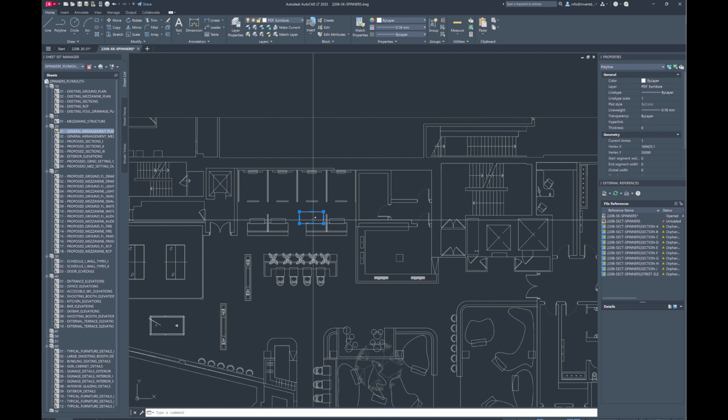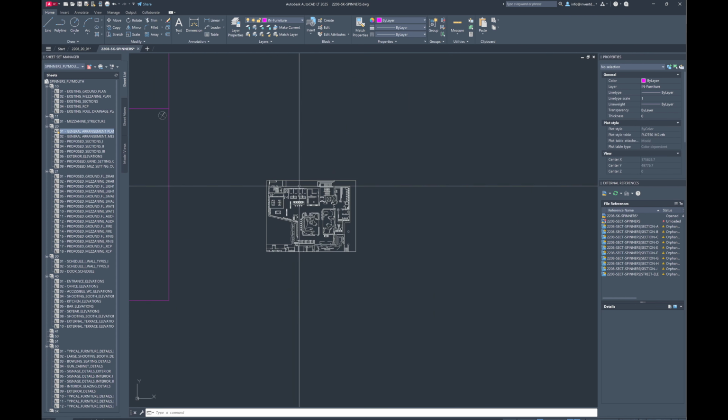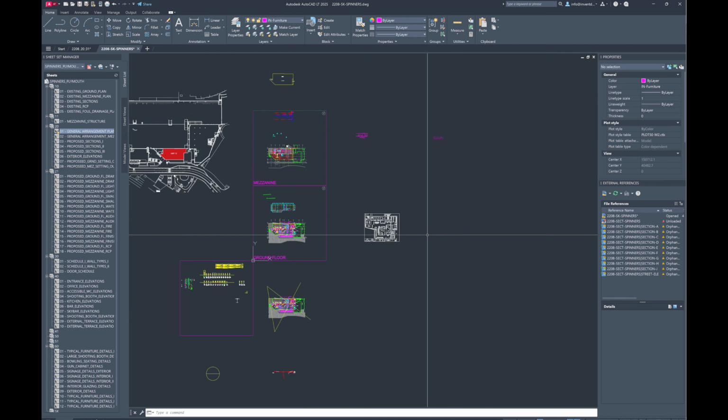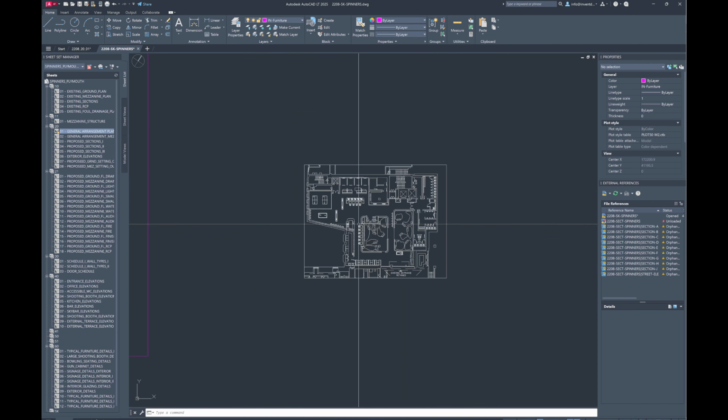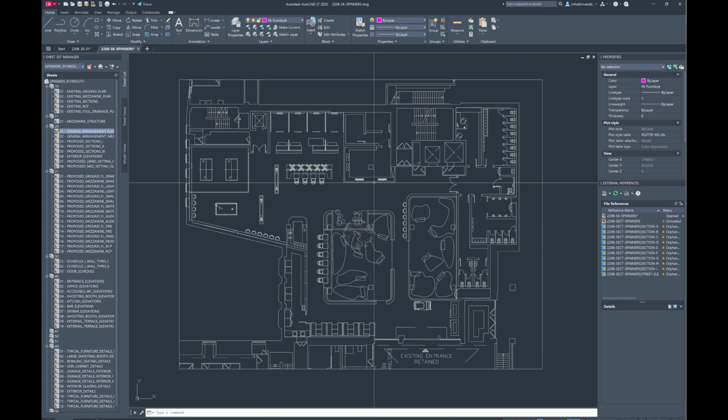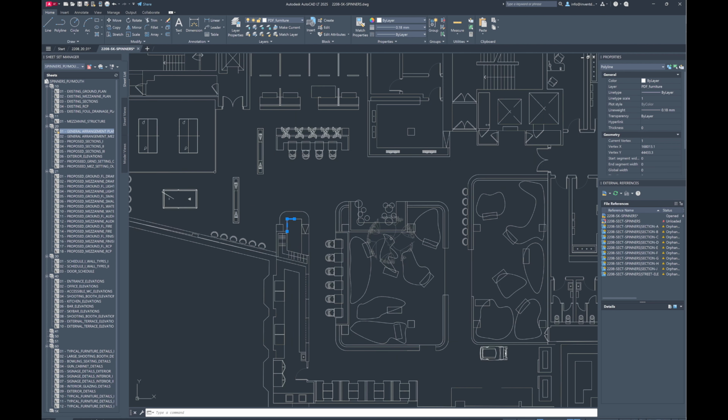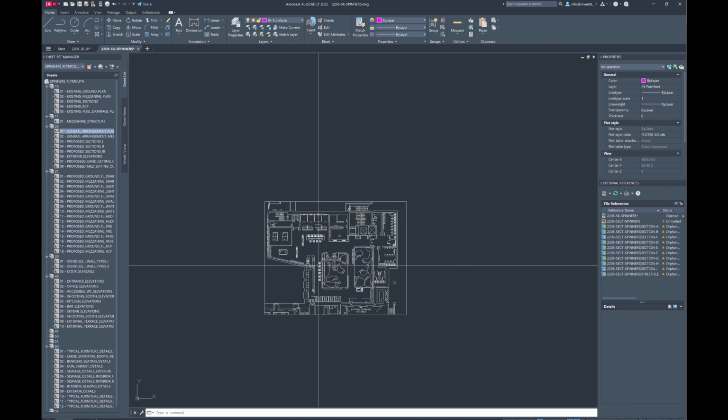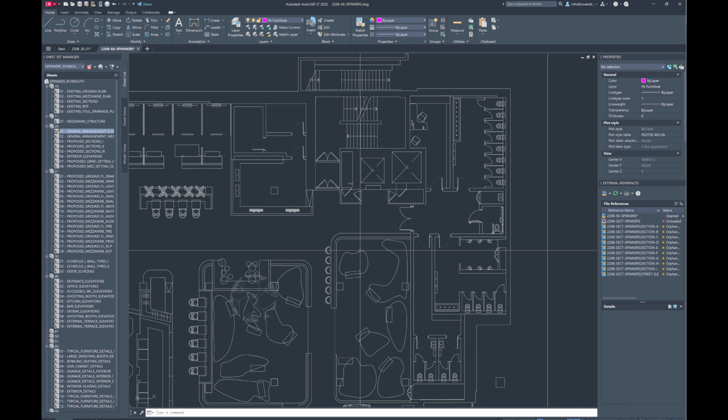So you couldn't actually do that in SketchUp, but what you could do is just use an external PDF to DWG converter. I think there's free ones online these days, and then do that as well. Obviously, that doesn't always work because if it's an image that's been converted into PDF, that's not going to work. It needs to be like vector files, which are lines that can be edited. So the way the file was originally converted is important. But you can see with that one that worked quite well, and all of a sudden I can use and manipulate the lines within this model.